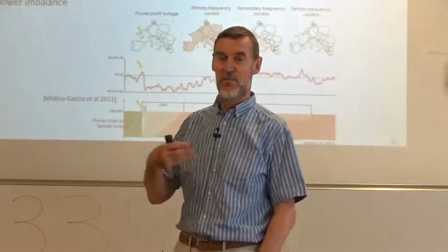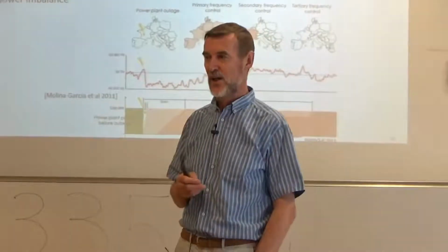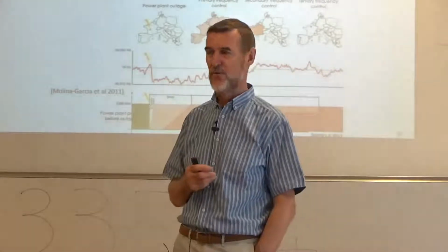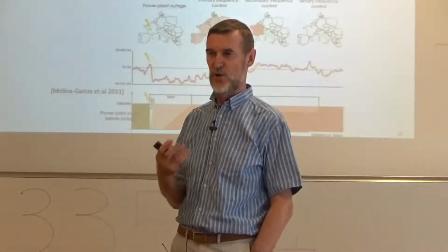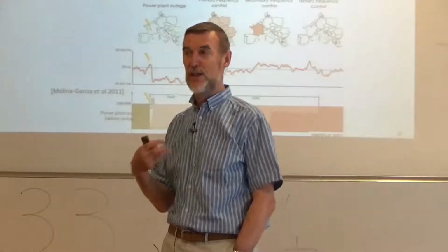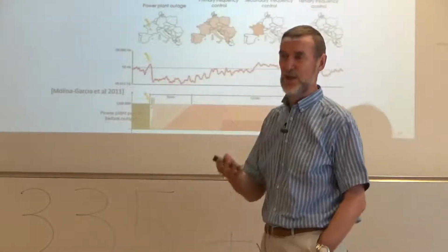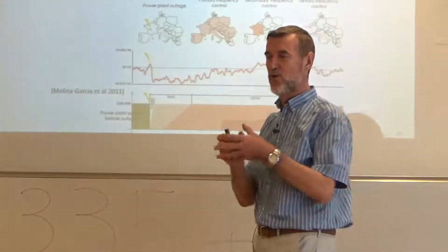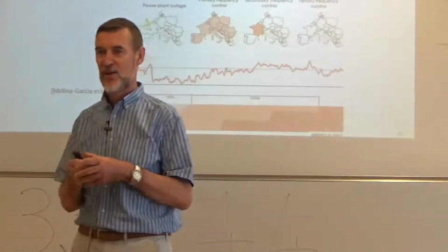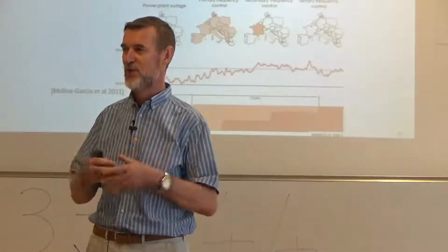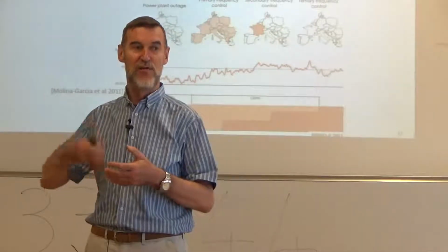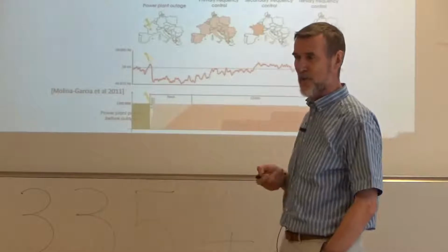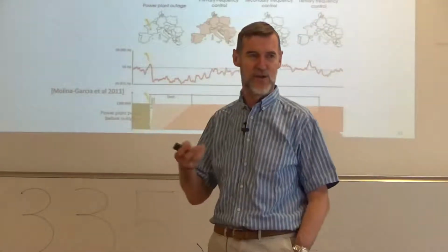right? So by slowing down, it delivers some of its mechanical inertia, which will dampen the overconsumption, but it will slow down. So slowing down, if the frequency is given by generators, means that the frequency also will go down. So if you have a small house in the Alps with your own diesel generator, and that's your grid, a diesel generator and the rest of your house, then the frequency will vary by huge amounts, not by small amounts like here, but it will vary dramatically. It will go down to 40 hertz, and you hear it.